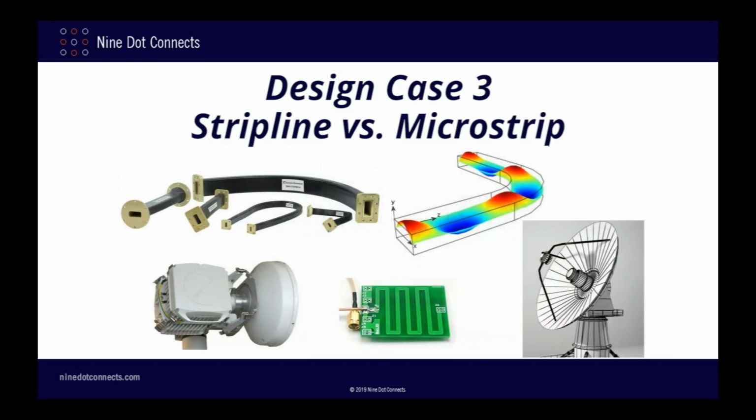Much like S-parameter graphs, this somewhat confusing terminology also comes to us from the world of microwave and RF engineering. In fact, the word strip line was actually once a proprietary brand name. The 2 technologies were originally developed to provide microwave componentry, such as waveguides, antennas, filters, and so on, and as such were greatly dependent on the geometric relationships between the copper and the dielectrics. As these same kinds of geometric relationships started transitioning to the world of high-speed PCB design, the 2 terms came along with the baggage. But instead of referring to the microwave aspects, they are now just mostly used as convenient terms for routing on the inner and outer layers.